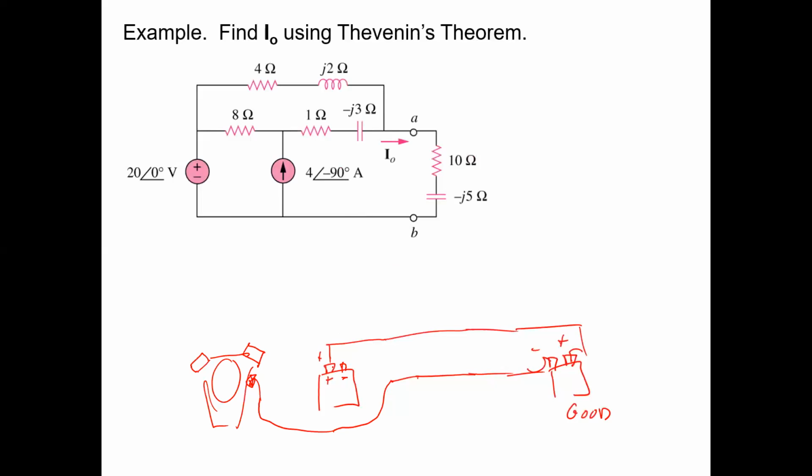Yeah. Jump in a car in a closed garage. Sometimes you have to rev the engine of the source car, give it a little more power, and that will raise the voltage. It's the alternator that's driving the battery, so when you speed up the car, it raises the voltage, and you get more power over there. Anyway, you're supplementing the battery of the bad car with your battery.